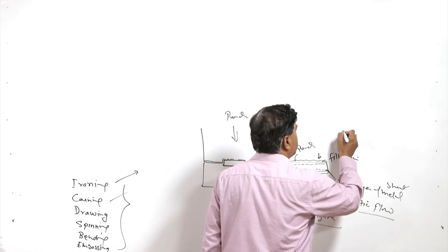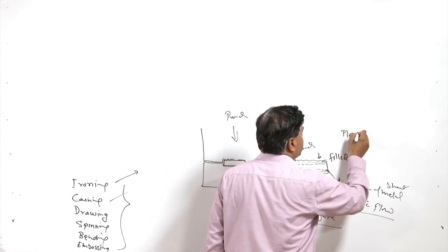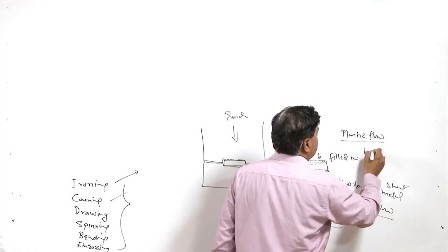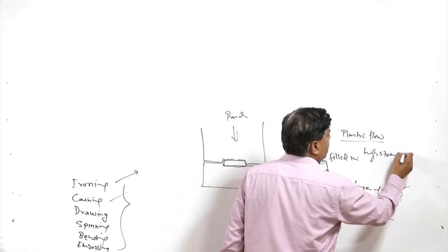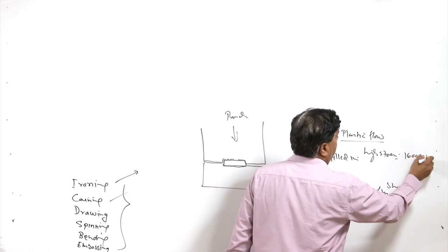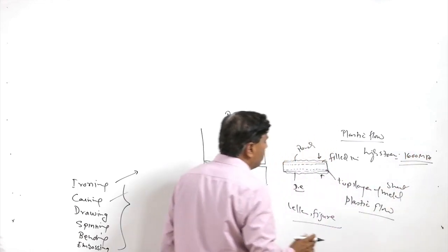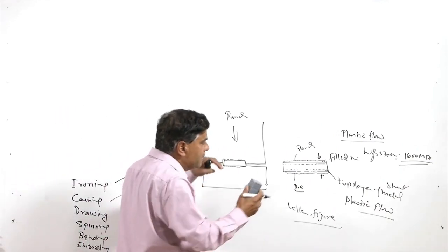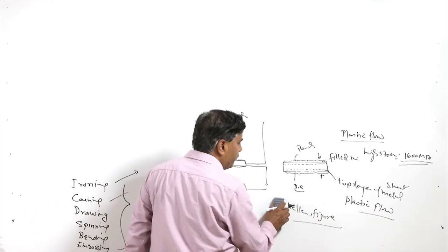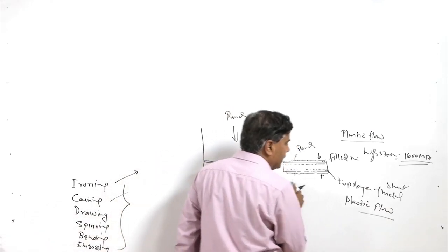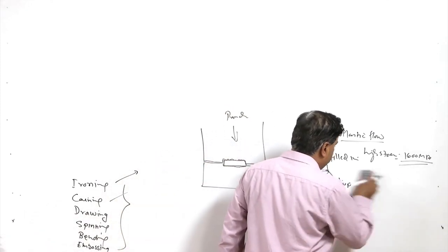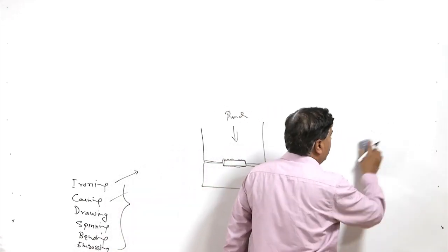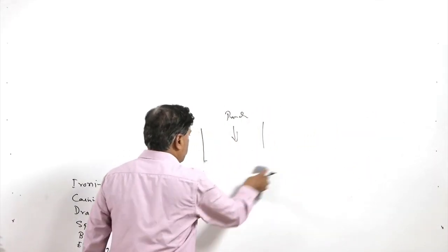For this purpose, the plastic flow is facilitated using high stresses, which may be as high as 1600 MPa. Because all this happens under compression conditions, the metal is forced to flow into the finer details present in the die as well as in the punch, so that the desired impressions in the form of letters and figures are produced in the coin.